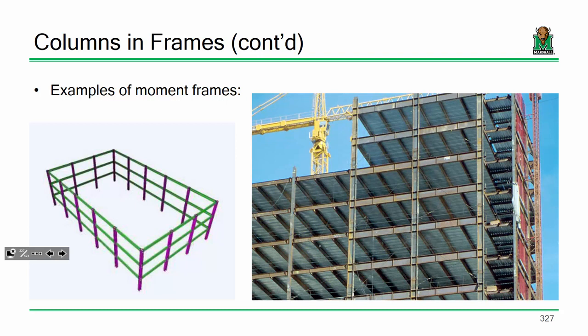For instance, let's take this building. This building has a moment frame, but based on the image, it looks like that moment frame is really only going across 2 bays of the building. Like there's a moment frame here and a moment frame here, and that's it. Make sense? If I were to extend that moment frame over here, and make more of this moment frame, I would have more moment frame members, but more than likely they would be smaller members.